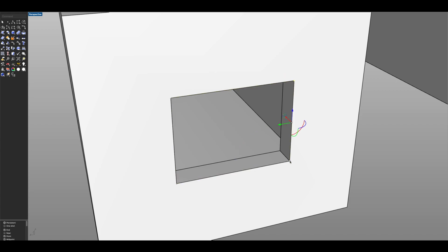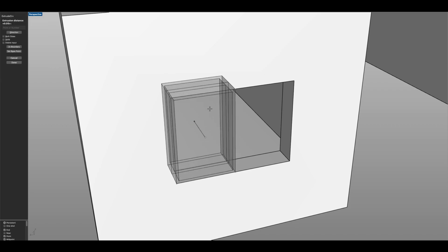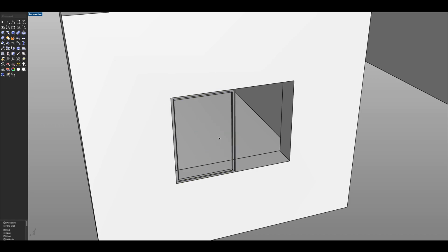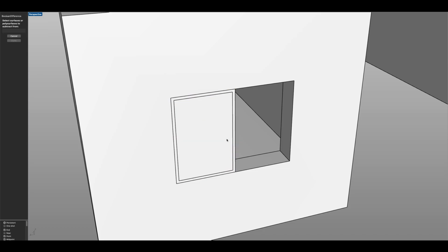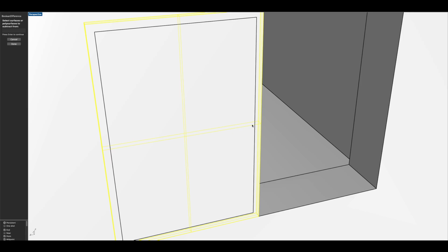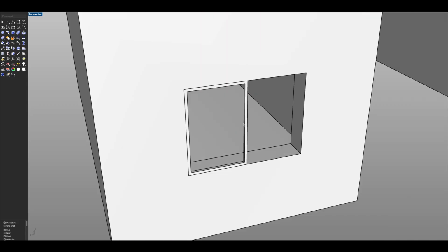On the back though, the lines are far simpler, so we can actually repurpose this one here. Let's pick up on these points, let's bring them over here. Now let's make an offset, like that. Let's select them both and go for an extrusion. Once again, 0.05. Let's delete those lines. Let's make new caps here. And now let's go for Boolean difference and go for 1, 2.